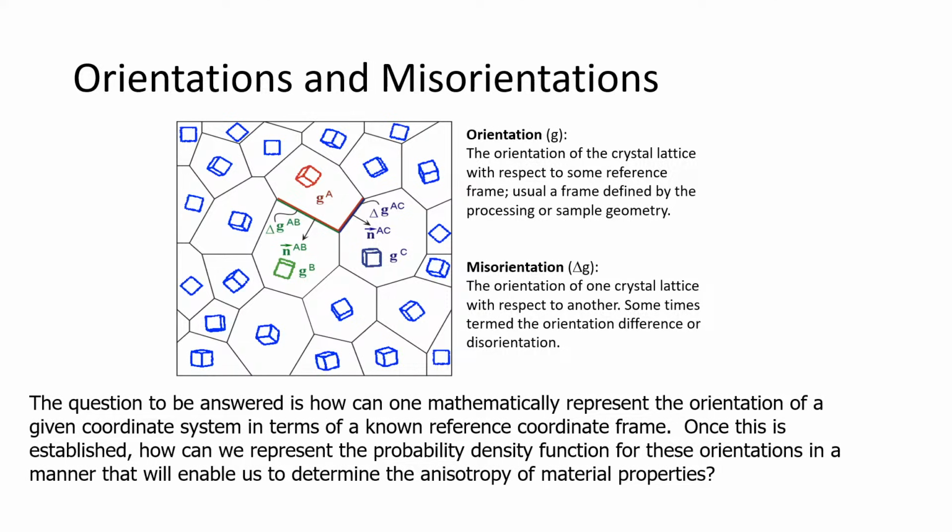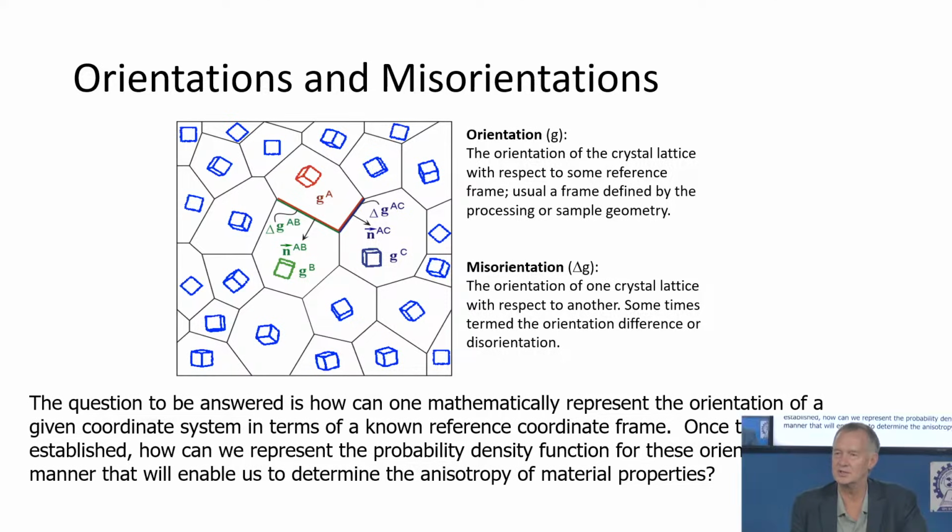So all of the conventions, you know, Bunge, Euler angles, Roe, Kocks, that's all I think of for now. Seems like I missed one though. Anyway, all of those use the same kind of conventions, right? All the passive frame. If we talk about a misorientation, right? A misorientation will take the rotation from one crystallite, right? The orientation of this one, rotated into coincidence of its neighboring crystallite, or into coincidence with some other crystallite somewhere else. That's called the misorientation between those.